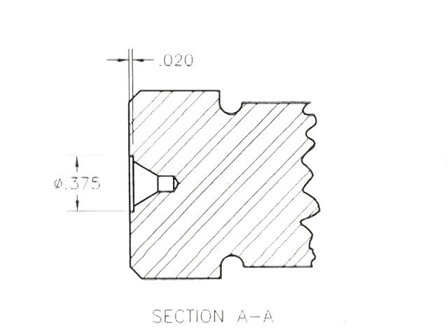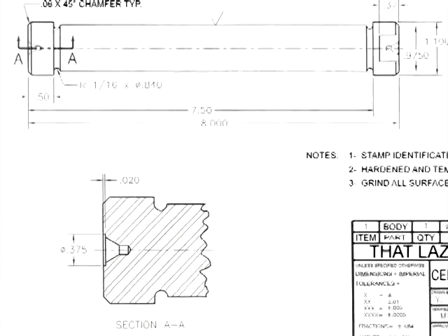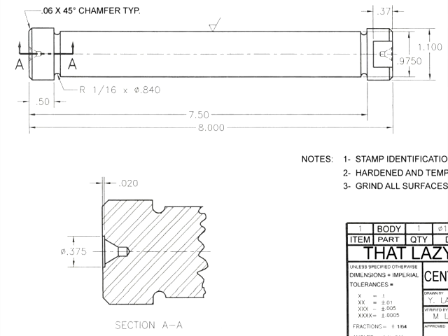And this section is not a bottom section view. It's not a bottom view. It's not part of the projection. Now, section views can be part of the projection, but in this case, since it's not at the same scale and it doesn't align with the rest of the drawing, we'll just call it a detailed section view.